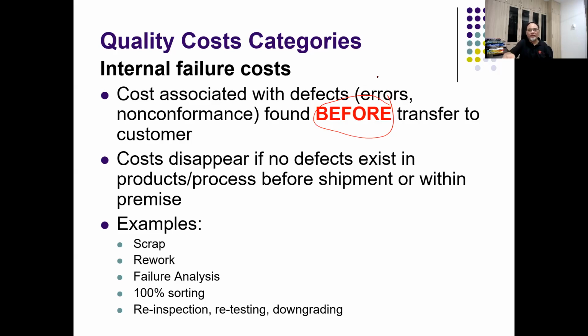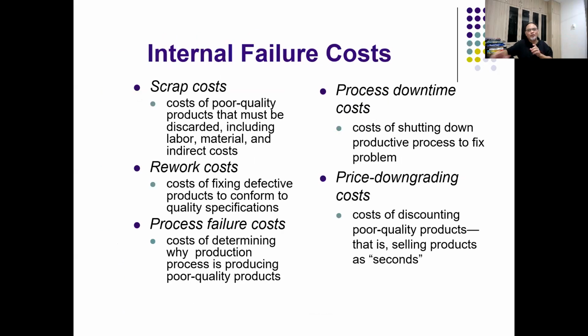If you detect the defect at the point of assembly, immediately you can rectify and replace. If it is in the next step, it is still much cheaper. If you detect the defect at the inspection area, it depends how far it has been processed, to dismantle it and fix a new one. Imagine you go out of the manufacturing premises or your operations, then the cost is already exponential, because you need to send your team to do the repair. You need to send a team, bring in the spare parts, meaning the components, and bring in the tools to do the replacement.